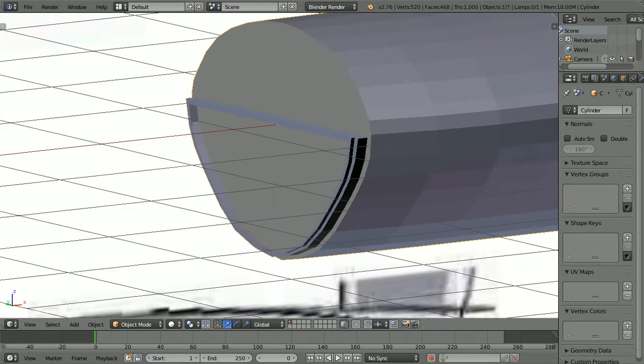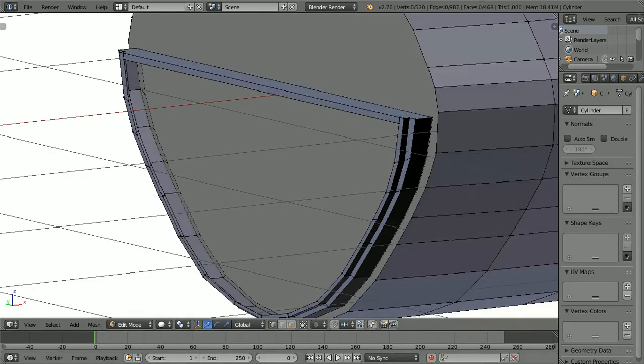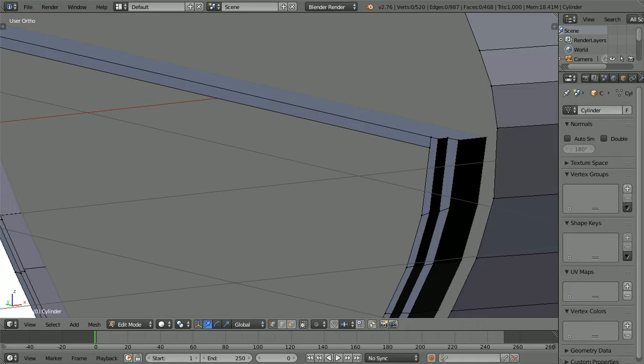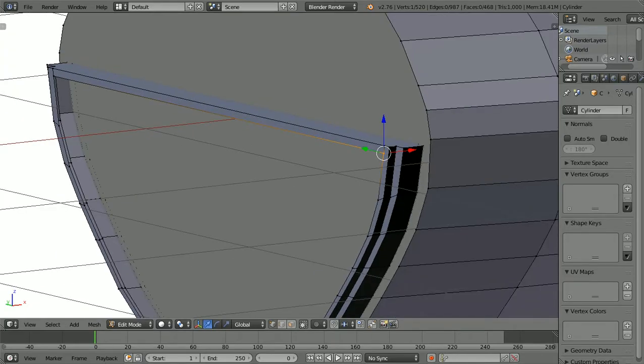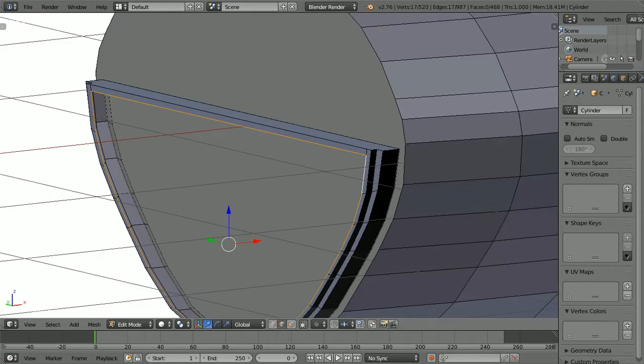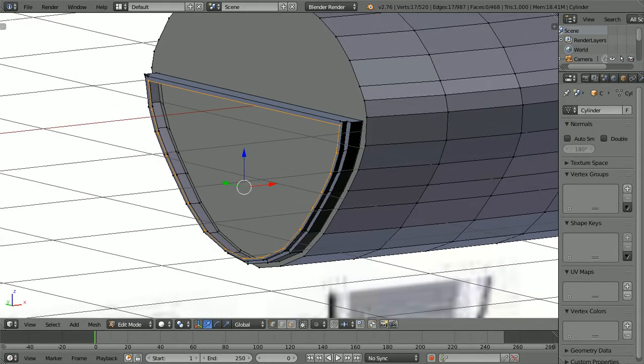Select this as an object. Let's go to Edit again. We're in vertex mode. So now what I want to do is actually select, and I'm going to use the boxing method. Or the other thing I could do, actually, push A. If I went to line mode, and I think I push Alt on this line, let's see, yes, it worked. See there, I got that whole inner line, which was what I was wanting to do. And then if I just click over to vertex mode, I still have all those lines selected.